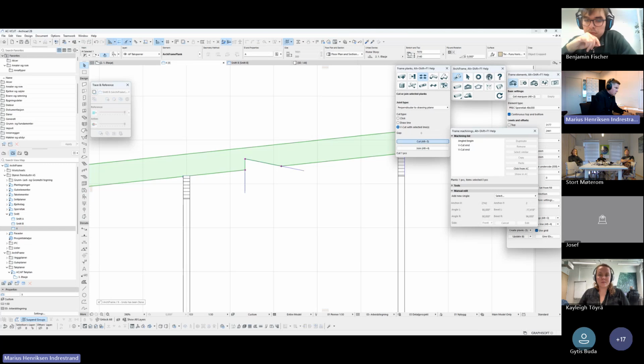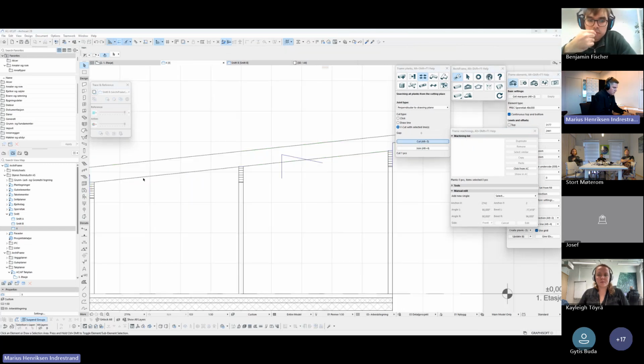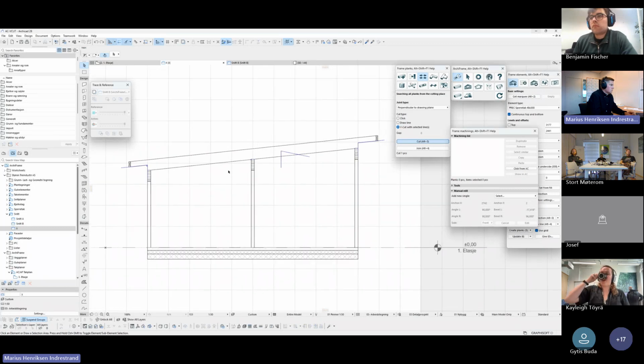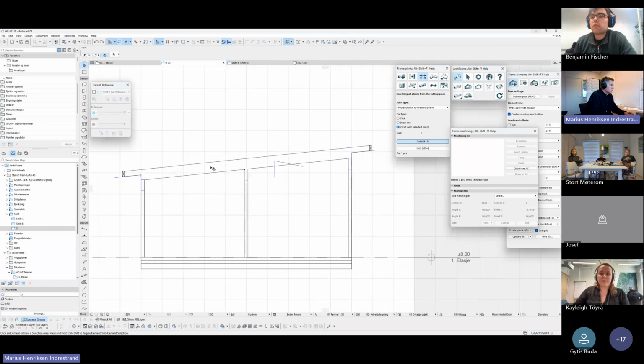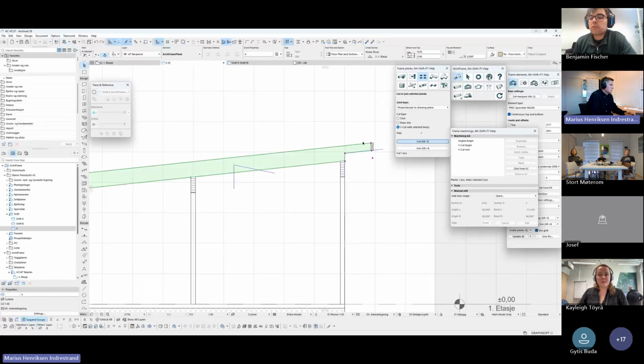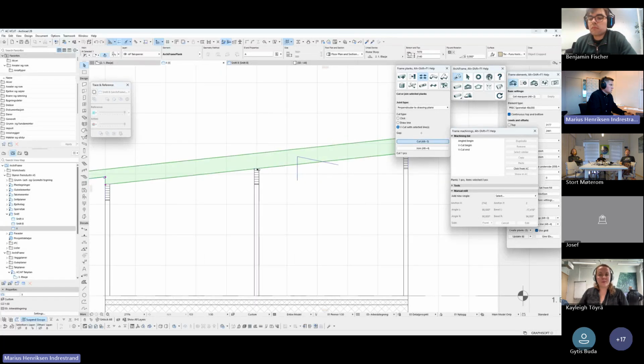Just gonna redo this. And I would suggest doing most of the work on the joist or beam before starting using V-cut, depending on how much other work or openings you are going to do. So let's see, we have done everything, we have a few V-cuts. I'm gonna cut this beam because I want to lift this one up. One way to cut beams is drawing a line, perpendicular, cut.